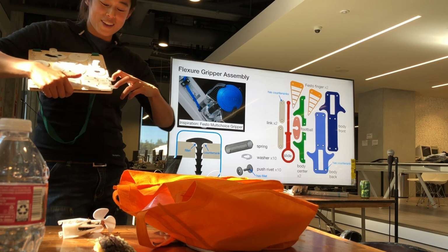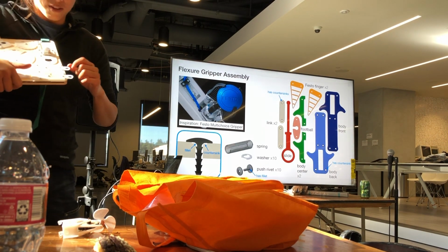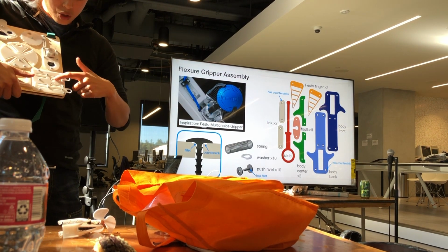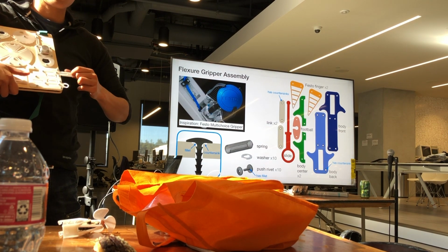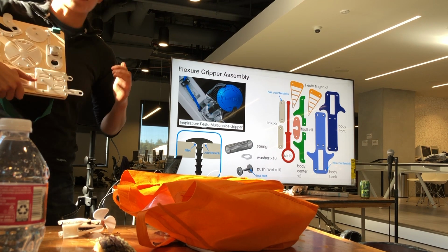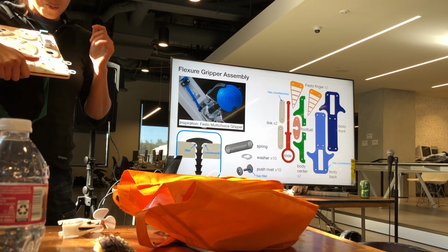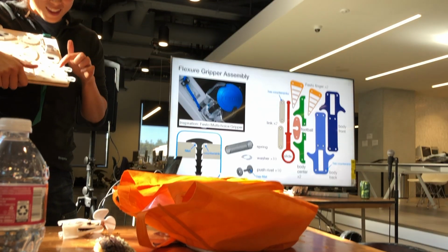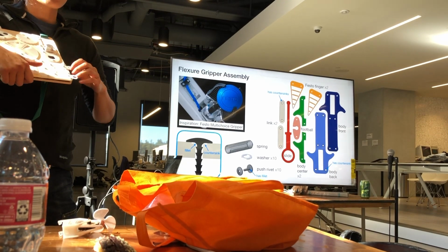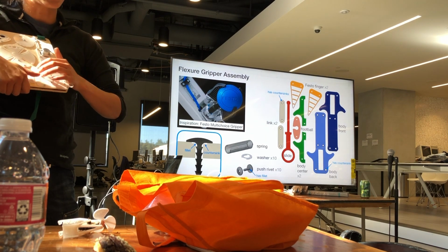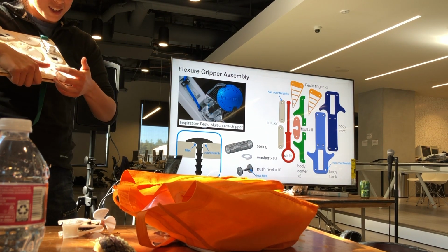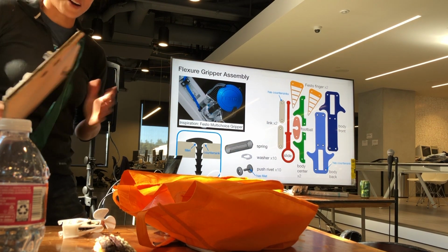This one, I designed the springs so they're a little bit too stiff, but if you look at it, there are 2 deformable structures in here. One of them is thinner than the other, and you'll see that reflected in the force it takes to pull them apart. Much less perceptible is that the detents are actually of varying depth, so if you're very slow and careful, you can detect a difference in the force it takes to push them in and out. But I won't be surprised if you can't detect that.